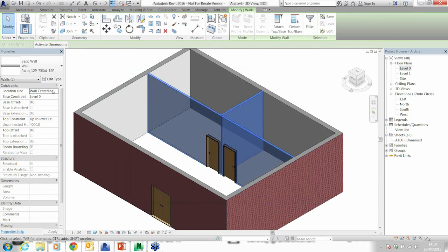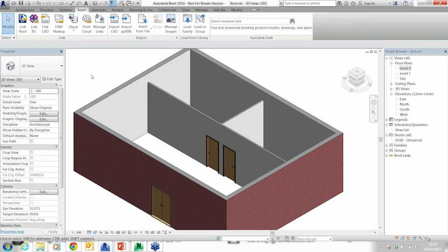I'm just going to modify these. I need to reduce the walls down; they're a little bit too high, so it's going up to the level. Top offset, let's put a minus, that's the extreme, put a minus 400 in there. Well, let's set that to get away, probably minus 600. Okay, so I've got a minus 600 drop on them walls.